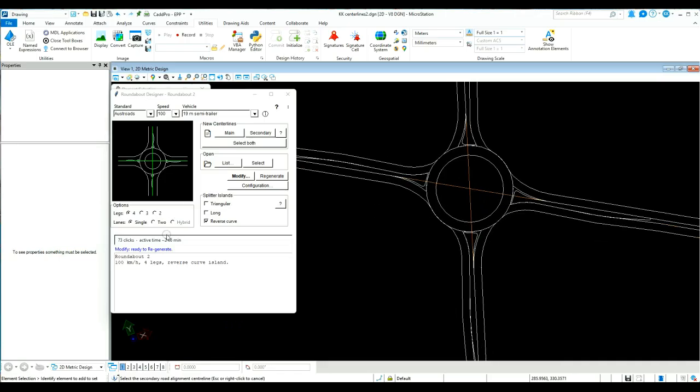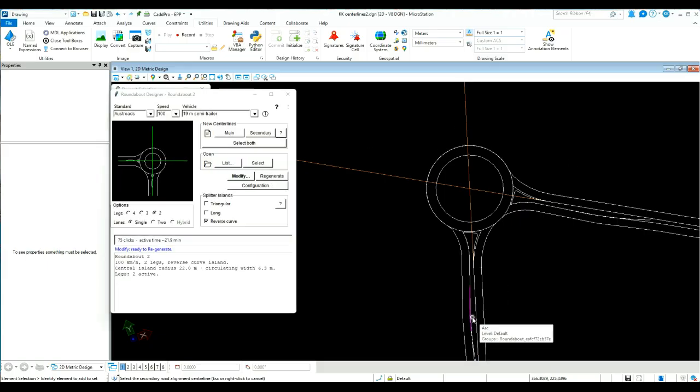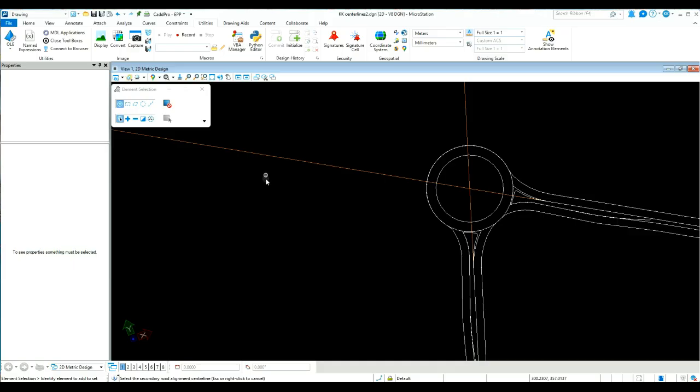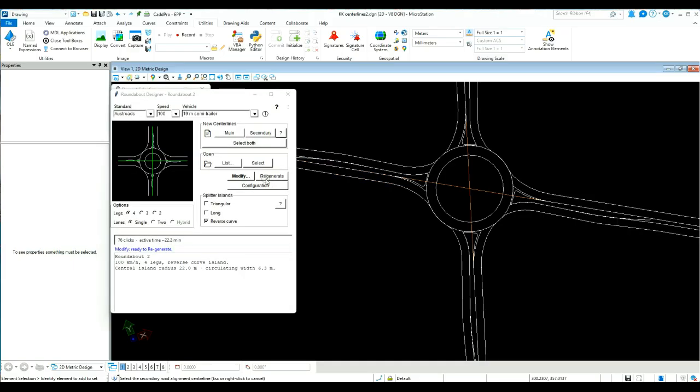And just to show you, if we selected 3 lanes and regenerated, because that was the second alignment, it truncates that, and regenerate for 2 lanes. Remember, I select that as alignment 1, 2. So it uses the position pick on the alignment primarily for that purpose. So we'll regenerate it. You can see the content is created fairly quickly.